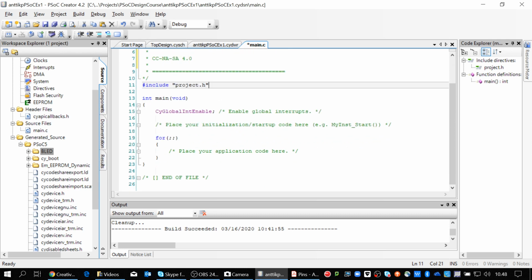Okay, what next? Then that's perfect as a program core right now. Usually on any of these bigger processors, there are always some interrupt-driven functions going. At some point you would be turning on the global interrupt enable. If you remove this line, none of the interrupts actually work. So just keep it. It doesn't hurt if you don't have any interrupts. But anyways, you need to have this one there.